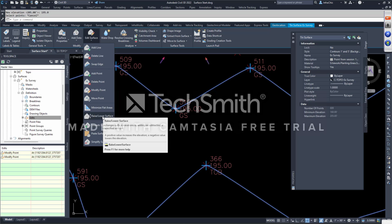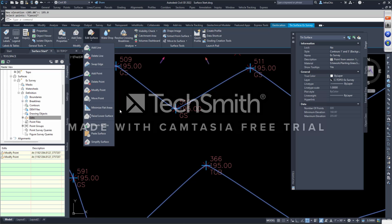GIS could be as old as 1972 to as new as last year. Okay? And it really depends on how good the clearinghouse is in the GIS database. But when I get my GIS data, a lot of times the datum of that data is different. I may have 195 here, and if I bring in my GIS contours, they may be 210.